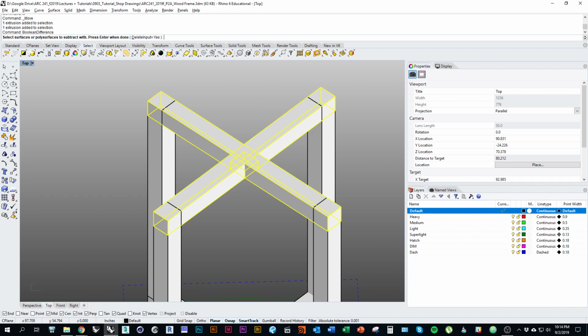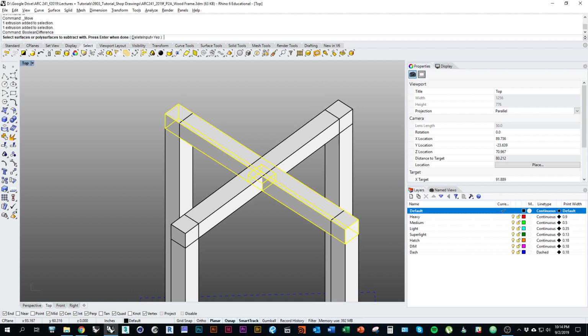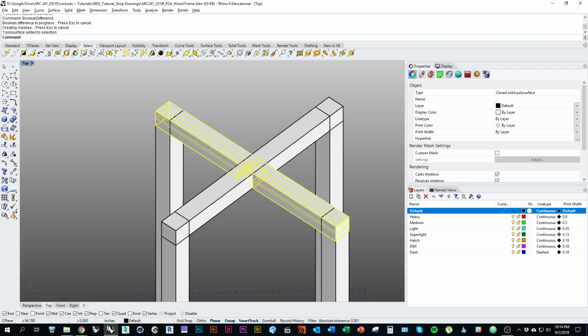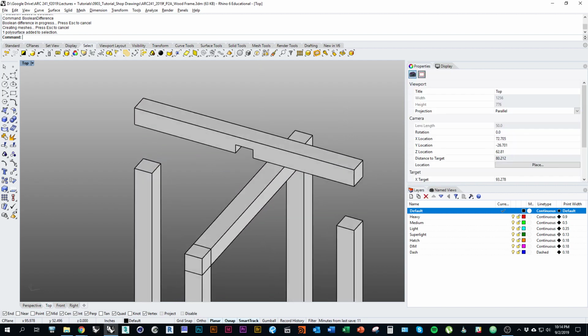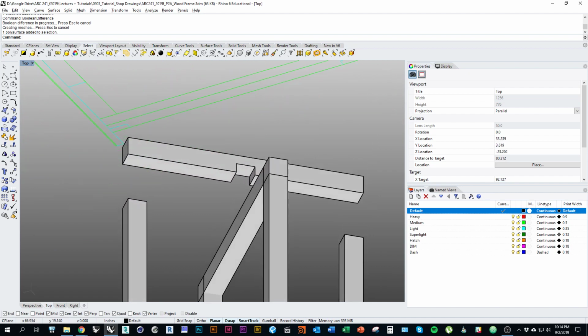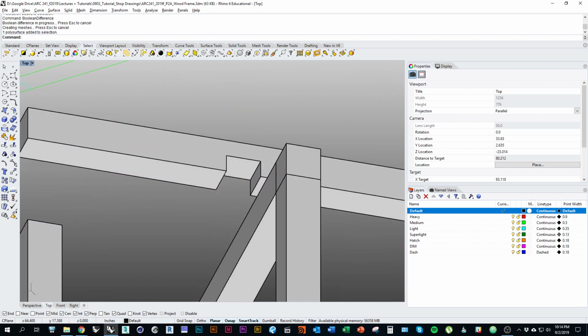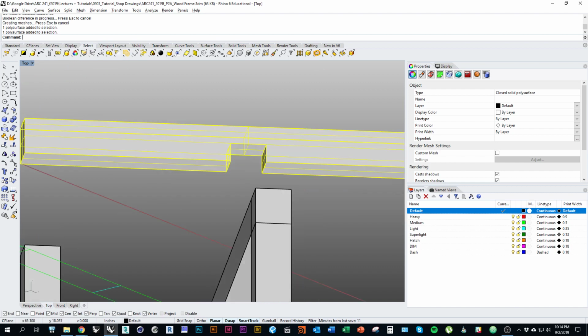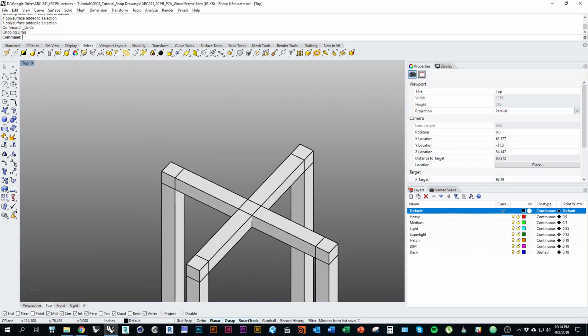And I don't want to select that line, right? So I can hold Control and click on it to deselect it. So I just want to click and drag to the right around my little box, just so I'm selecting that one object. Press Enter. Okay. And then when I go ahead and select this object, you can see that it has this cut. So like I was saying, because we're using solids and Boolean operations, it's already formed a closed interior face where we made that subtraction. Okay.